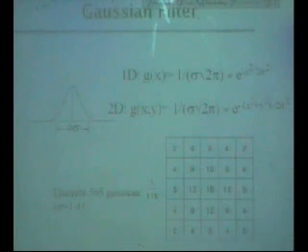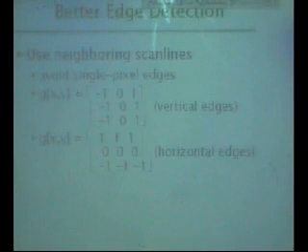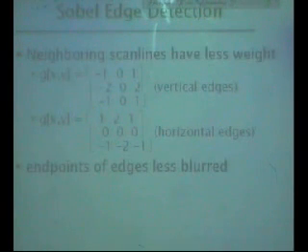And how many? 3 by 3, or 5 by 5, or 7 by 7, or 9 by 9, you don't know. In this example these are 5 by 5. So you are computing this value, and for every pixel you need to do 25 multiplications and 24 additions. So you do this. Gaussian edges are sharper than the boxcar filter. This is the edge detector. It'll work like this. Again, these are the two matrices, and these are other edge detectors.